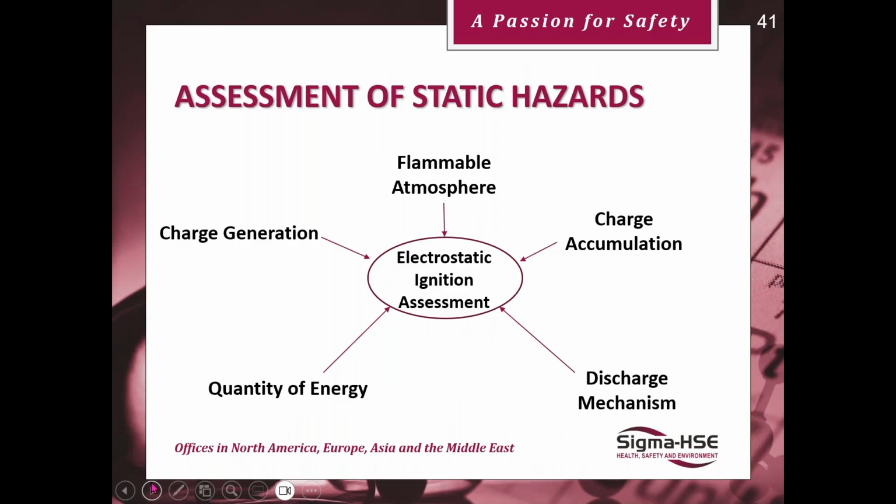So, assessment of static hazards. Do you have a flammable atmosphere? Can you generate charge? Are some of your materials insulating, for instance, so they can generate lots of charge? Can that charge then accumulate? How much energy can it produce? And how does the discharge of that energy work? This is an electrostatic ignition assessment. These are the facts that you're going to need to put together, so that when you do an electrostatic ignition assessment, you have everything at hand.